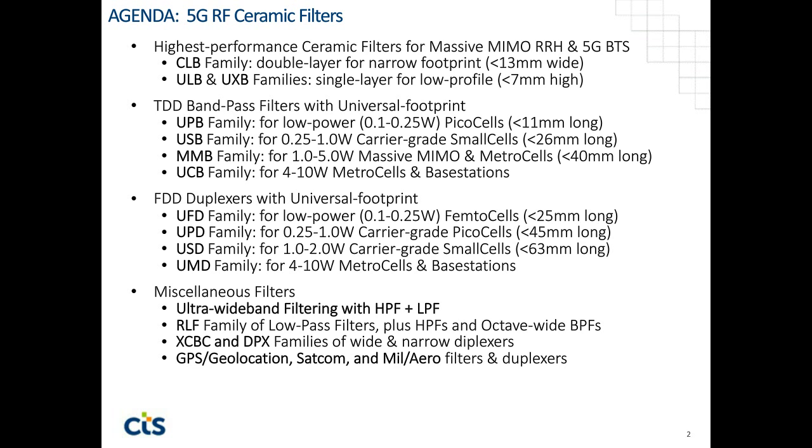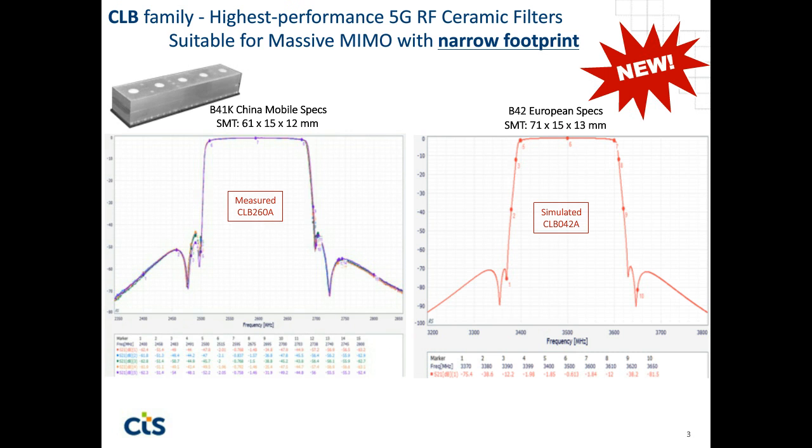In the most demanding applications, where it may be, for example, a massive MIMO system with extremely close-in rejection requirements, which, let me emphasize, is not true for all frequency bands, but here we've illustrated two frequency bands which are well known to require extreme close-in rejection performance.